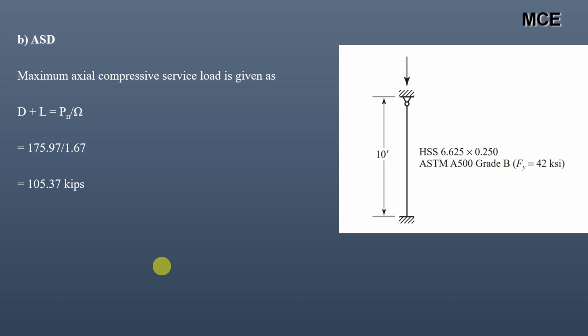So this is how you can find the maximum axial compressive service load for a column using the AISC equations, both for the LRFD as well as the ASD.